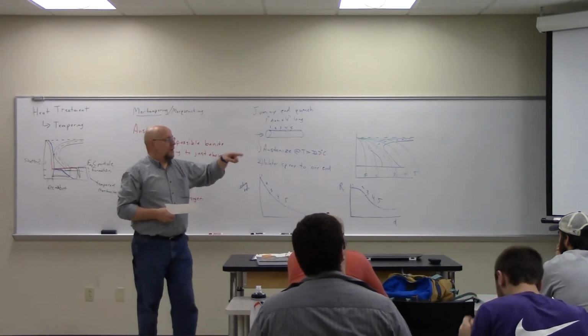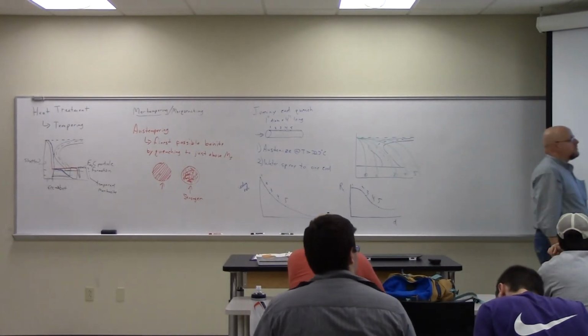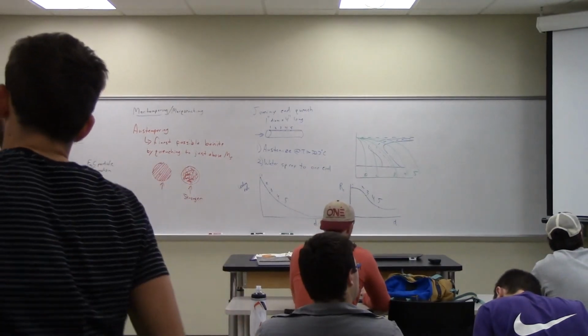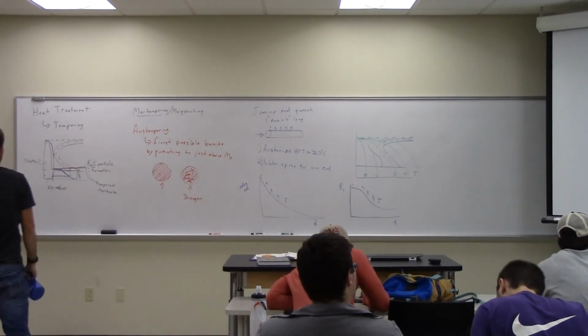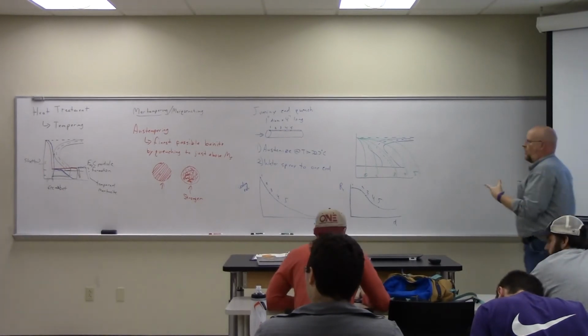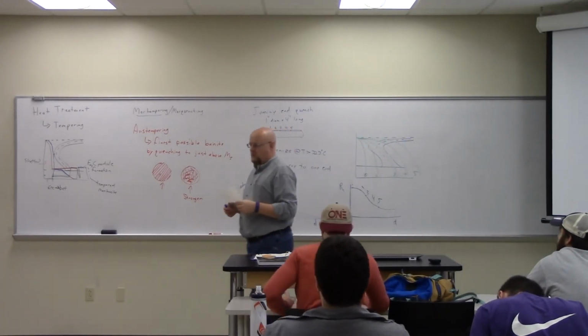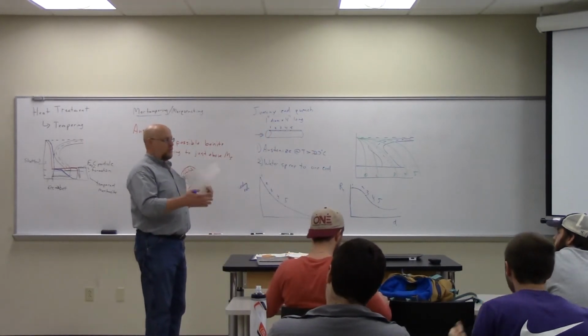Right? So all of these are using compositions between 0.02% alpha, which is the peak of the alpha, and 0.77%. Right, so these are all for low carbon steel. But there's also the possibility of doing precipitation, doing hardening for things that don't go through eutectoidal composition.